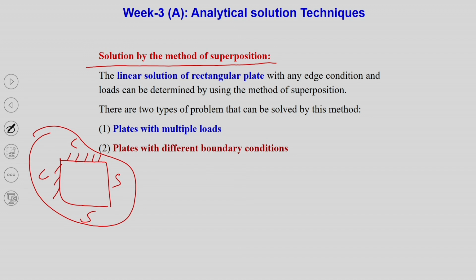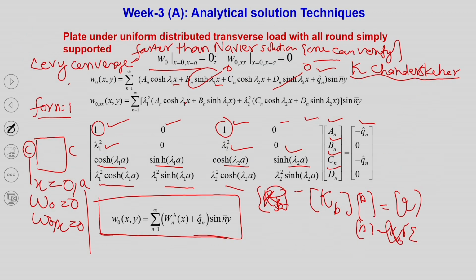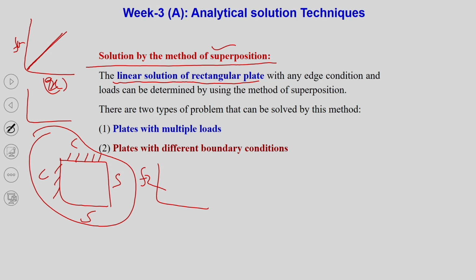The very first condition is that it is a linear solution of a rectangular plate. Whenever your deformation is small and governed by the linear equation, only then can you use the principle of superposition. The concept behind that: let us say any function f1 under some loading on x is going linearly, and some other function, let us say f2, on the same x is also going linearly.